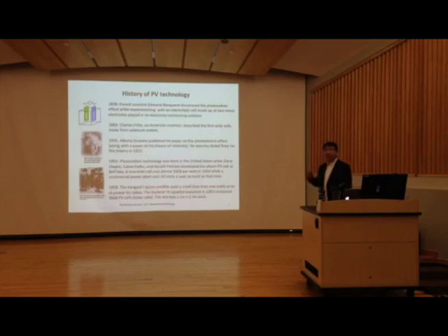Because if you want to send a satellite into space, we are looking for a source of electricity, and the satellite can see the sun. So basically, if we use a PV cell, we should be able to get electricity from the sun. So in the 1950s, people tried to put solar cells into satellites. For example, in 1959, that satellite actually had 9,600 PV cells connected together in series and in parallel in order to power the satellite, only for the electrical part. And if you look at the size of the solar cell, it's pretty small. It's only 1 centimeter times 2 centimeters each.